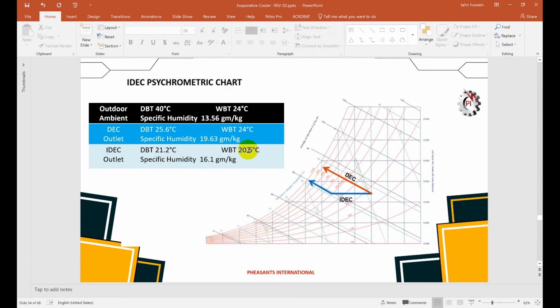The wet bulb temperature will also decrease, because we did the heat exchanger process and no moisture was added up to here. The sensible heat is reduced, while the dew point temperature and specific humidity stay constant.